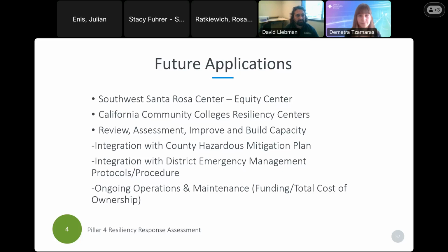We are participating in a number of demand response and automated demand response events, and working actually with the California Energy Commission's new demand response center to focus on accepting pricing signals to really optimize demand response or load optimization. One of the things I'm excited that we're trying to pilot is utilizing heating and cooling demand response. But should someone be uncomfortable and we allow a building to cool or to heat, our battery would then discharge to really firm up the expected kW reduction. We see this as a really important way to help the state future-proof demand reduction in its demand response program.